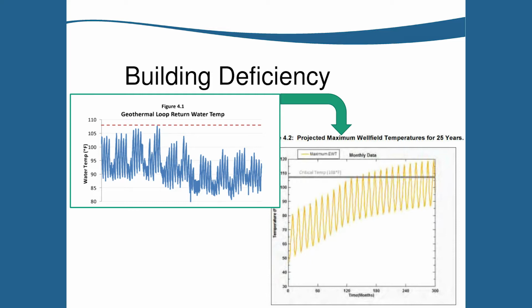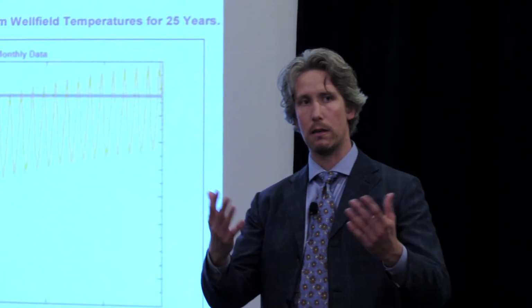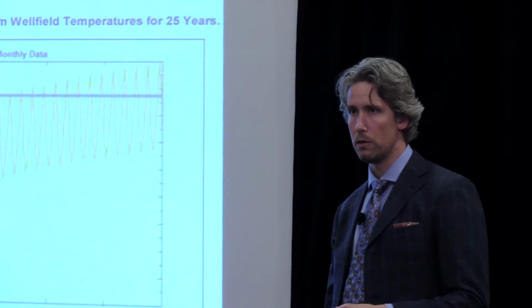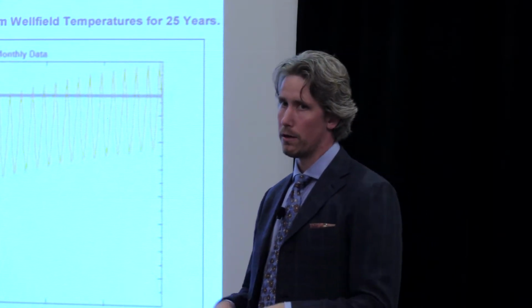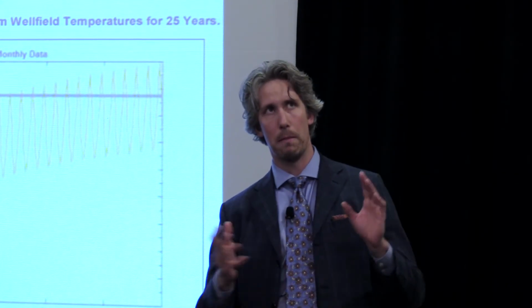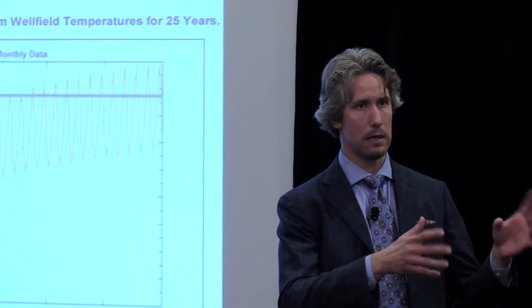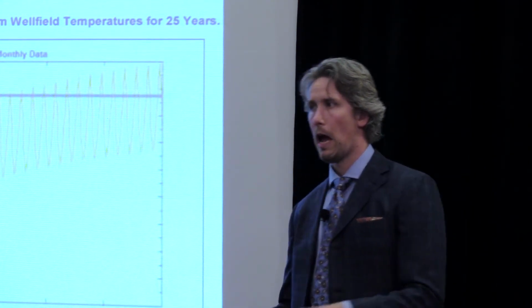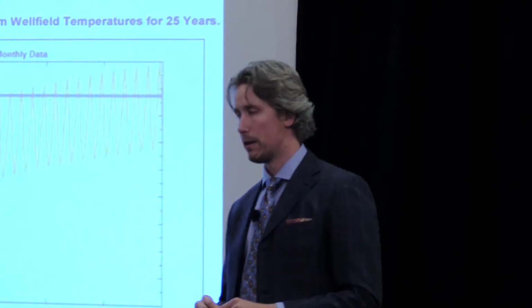So, quick background that's pertinent to the story. This system takes heat out of the ground in the winter and uses it to heat the building. During the summer, it puts heat into the ground as you're cooling the building. And so this system really only makes sense in areas where you're taking about the same amount of heat on an annual basis out of the ground to heat the building as you're putting back into the ground when you're cooling the building. Happens to work good where I'm from in Iowa. Probably not such a great idea in Orlando, Florida.